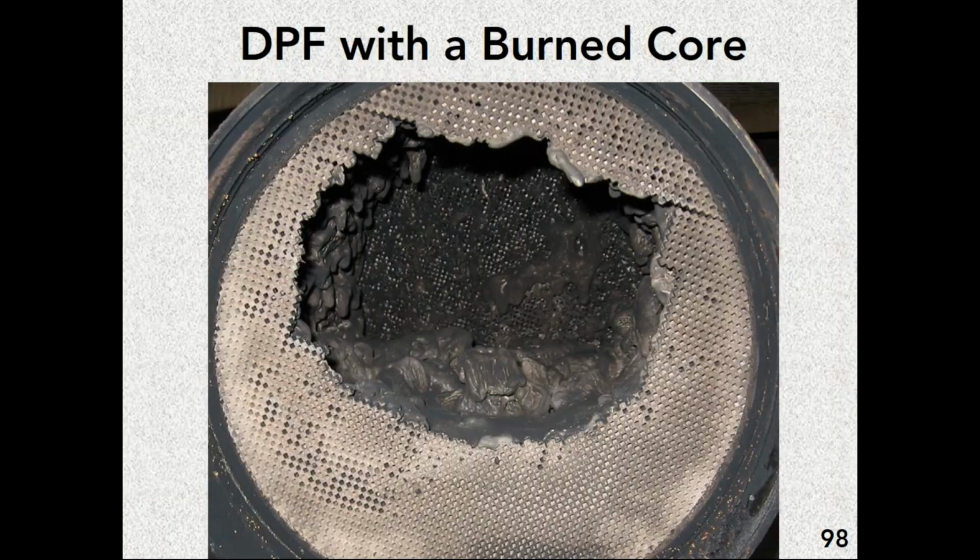Here's something that happens when the filter core gets too plugged and it's not taken care of. This was a runaway regeneration where there was so much soot deposited or raw hydrocarbon, maybe in a liquid form, in this filtration system, that when it started to get heated up because of the plugging, it ignited and burned through the core. One thing you should know about this is even though these filters are built to contain the heat and the temperature associated with them, this device, when this was happening, was probably so hot that the core itself was white hot. Dangerous, dangerous situation.